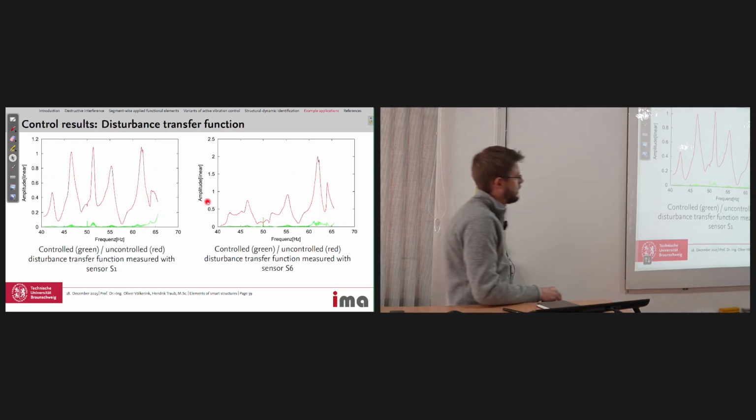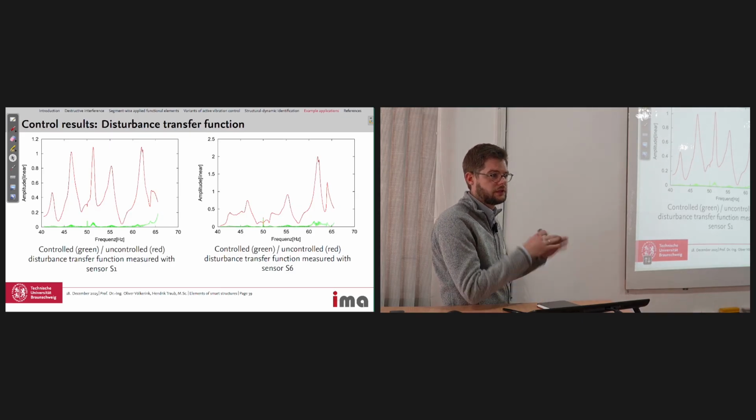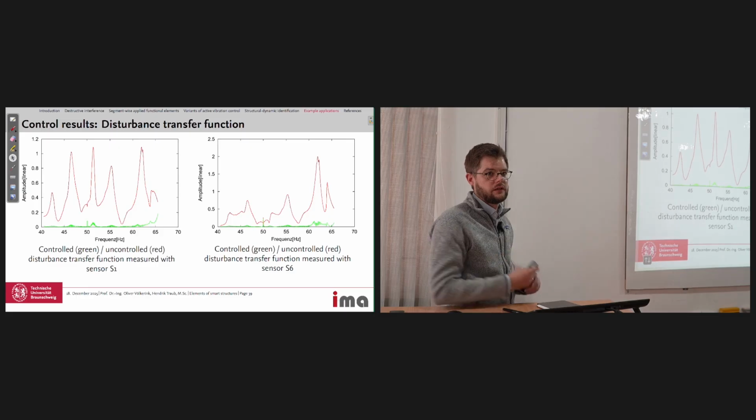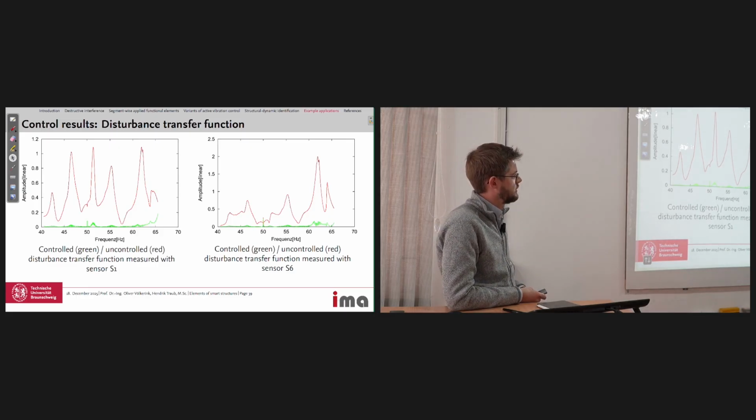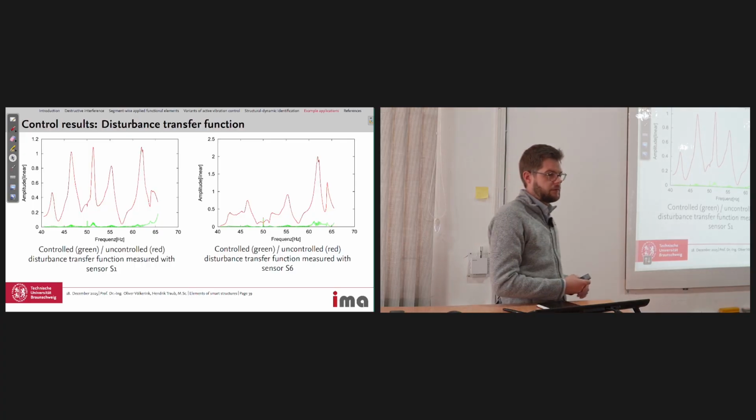Yeah, and I think in real structures, the influence of the higher eigenfrequencies decays, so maybe you have to look at the first 10 eigenmodes to completely or nearly suppress all vibration. I mean, you can perform finite element based modal analysis.